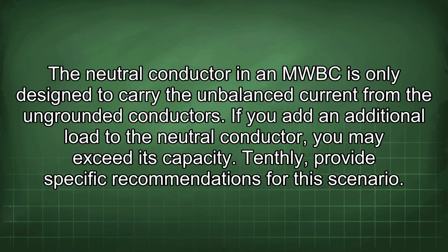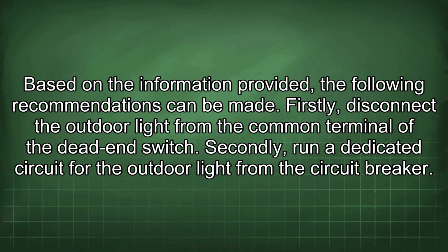The neutral conductor in an MWBC is only designed to carry the unbalanced current from the ungrounded conductors. If you add an additional load to the neutral conductor, you may exceed its capacity. Tenthly, provide specific recommendations for this scenario. Based on the information provided, the following recommendations can be made. Firstly, disconnect the outdoor light from the common terminal of the dead-end switch.